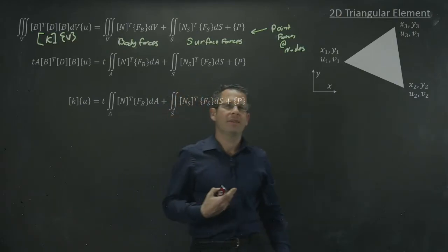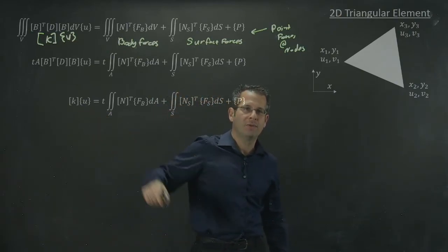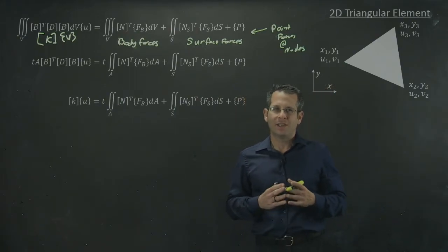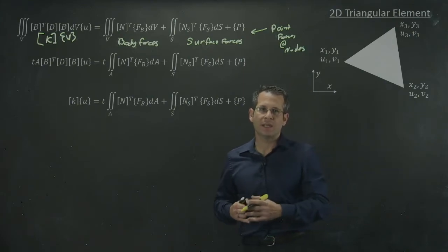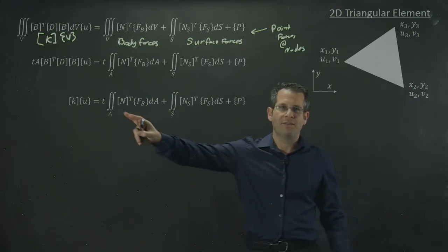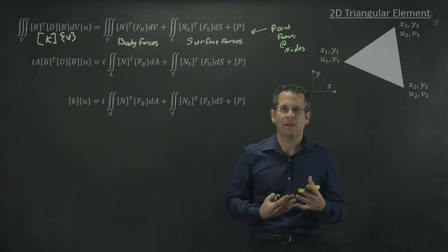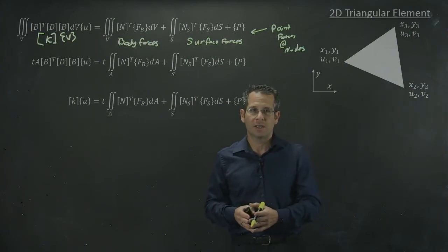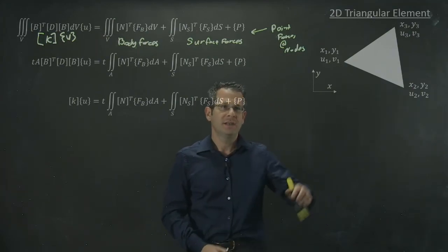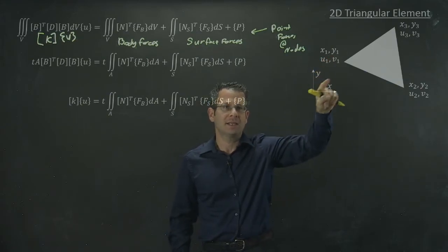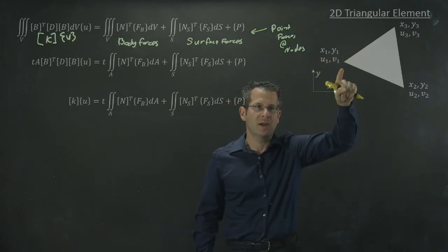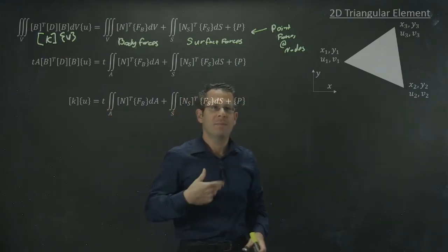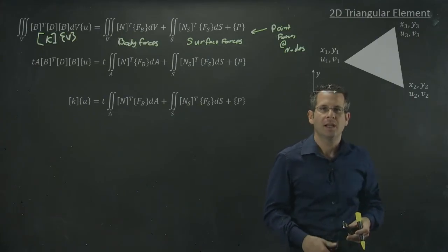I pointed out that while the formula for the K matrix is given in your textbook, I don't actually encourage you to use that formula to derive this K matrix. At this point in the course, it's better to write a MATLAB or an Excel spreadsheet subroutine that, given your xy coordinates for the 3 nodes, derives the alpha, beta, and gammas 1 through 3,